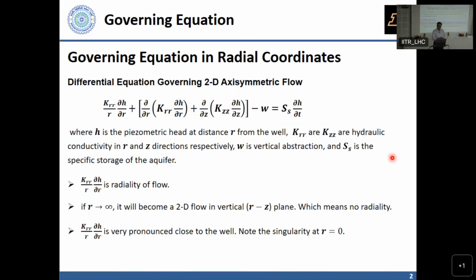Okay. So let's get started by looking at the general equation first for movement towards a well in the subsurface medium. And we have the typical terms, just that we are exploiting the fact that the variation is only in the R direction, where R is a distance measured radially from the center of the well to some point. And for radial symmetry, angle theta does not matter. In other words, there's no change occurring in theta.